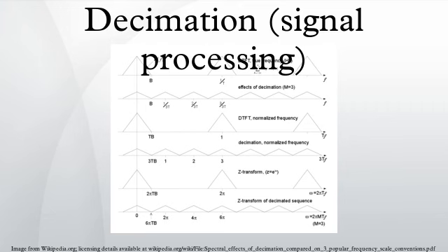In the middle pair of graphs, the frequency variable has been replaced by normalized frequency, which creates a periodicity of 1 and a Nyquist frequency of 1/2. A common practice in filter design programs is to assume those values and request only the corresponding cutoff frequency in the same units. In other words, the cutoff frequency is normalized to the units of this quantity: cycle per second equals cycle per sample.